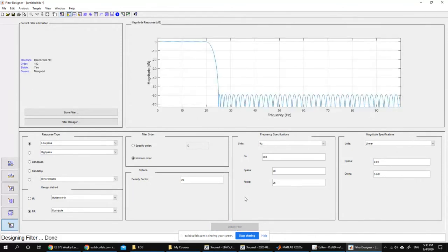Looks like this. This is basically the characteristics of the filter. You see here some very small variations, but actually all of them, the magnitude here is in decibels. If you have 1/1000, it's -60 decibels. So here you see that all the parts in the stop band will be below -60 decibels, which satisfies this. Okay?